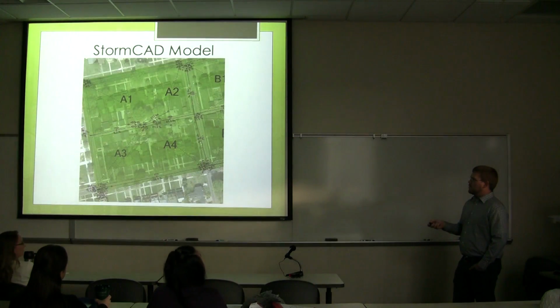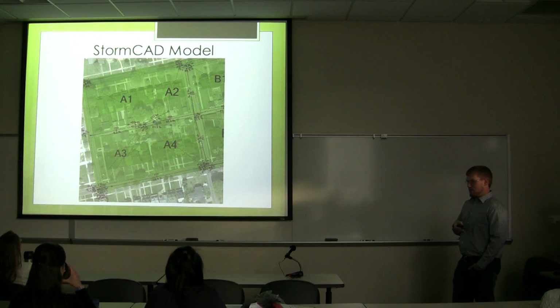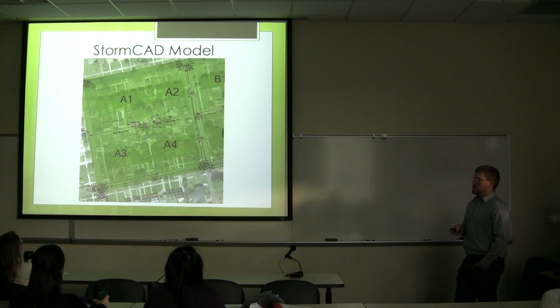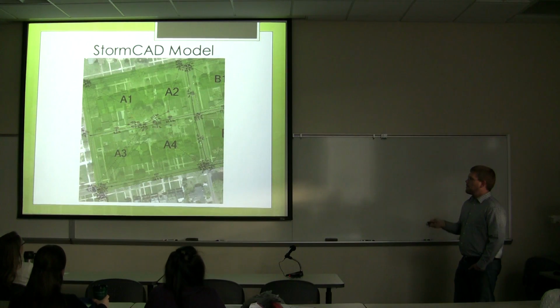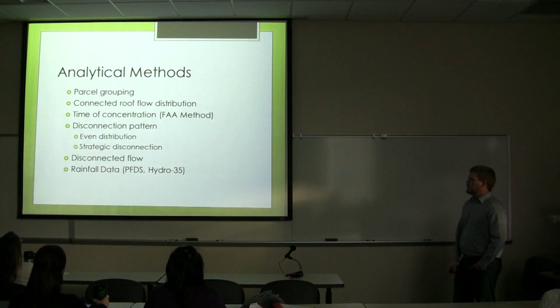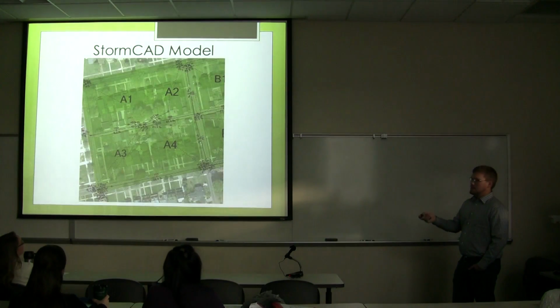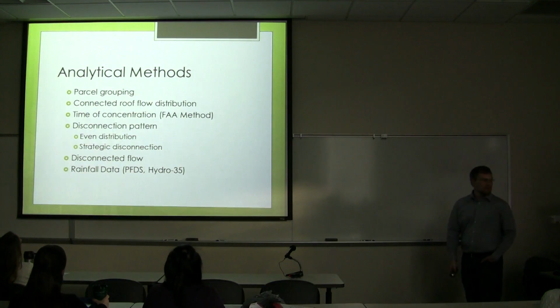So we assumed that it would flow from the roofs of the houses through their downspouts into the yard, and then follow the same path as the surface flow into the catch basins. And this would decrease the C value for the overall roof from about 0.85 to some lesser value we didn't calculate, but it would overall raise the weighted average of the overall catchment for the surface flow a significant amount. And this allowed us to determine our matrix, as Dr. White mentioned, and find our results.